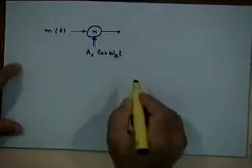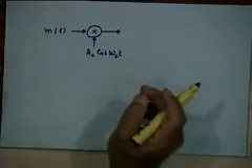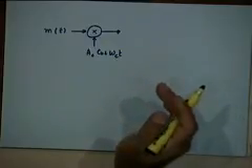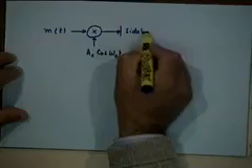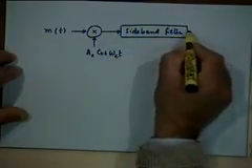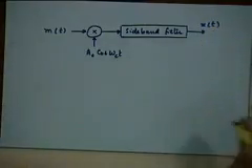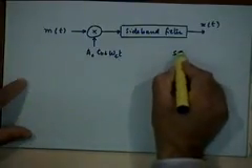And what should you do next? This will generate the double sideband signal. You want to remove one of the sidebands. You have to have some kind of a filter, a suitable sideband filter. Right? And that will be now your transmitted waveform or modulated waveform x(t), right? So that's your SSB modulator.